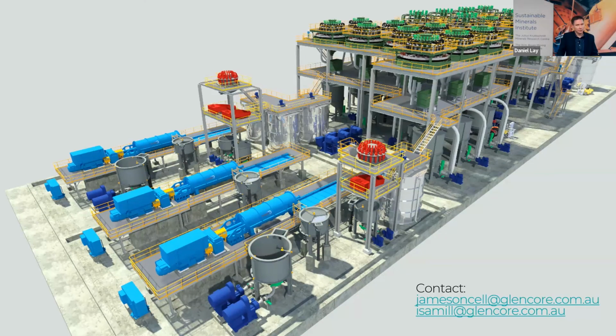That should give you almost 100% chance of collision. Where you can lose it is as it comes up to the froth phase, and that's really what's driving the selectivity. As it comes into the froth, there's a probability of detachment. Within the froth, running a higher froth depth, you would start to run lower froth recoveries. And essentially, that's where you are choosing which particles you're going to take and which ones you aren't.